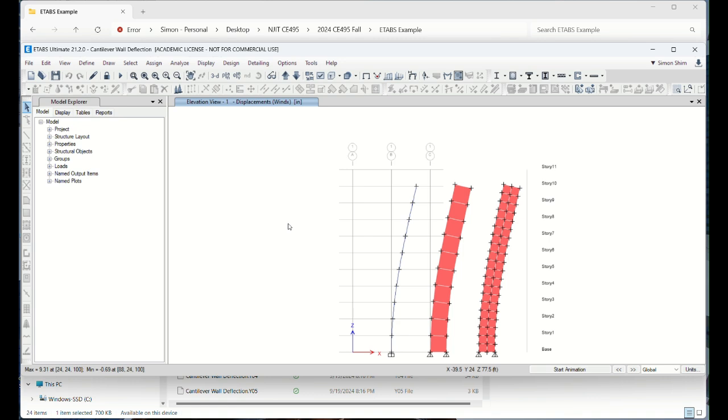There could be a lot happening, right? Concrete shrinks, elongates under the bending, right? But since this is big and the coarse mesh has only a limited number of points, obviously it has a tendency to overestimate the stiffness. Since I meshed it, I think we allow certain internal displacement and internal strain to happen. So we eventually end up with a little more deflection,